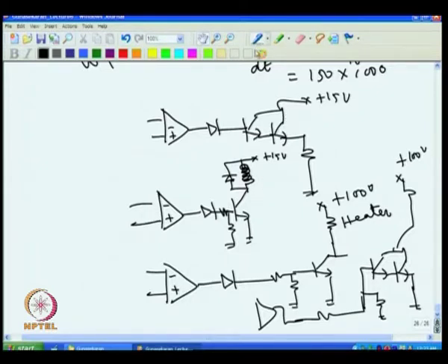the actual power is going through the contact here. And this is actually when the voltage goes high and this transistor conducts and full heater voltage is applied, because here we can go more than 15 volt, whereas in this case the heater voltage will not go more than 15 volt, because this can go only up to 15 and this will be 14.4, 13.8. So, roughly around 13-14 volt only you can get on the heater, not more than that. So, this is not possible.